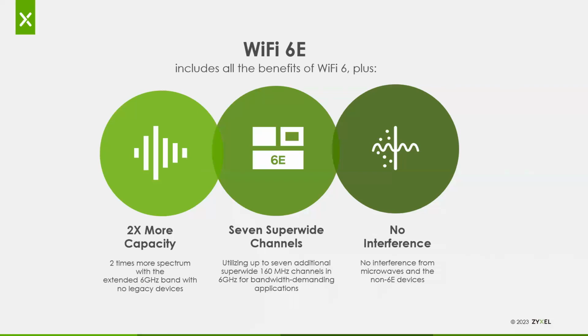But that does lead us to one key thing when it comes to Wi-Fi 6E and 6 gigahertz usage: essentially at this point, 6 gigahertz can only be used indoors. There is a new technology that is going to be part of being able to use 6 gigahertz outdoors. It requires you use a third-party service to be able to geolocate where you are, what channels you are currently using, and what channels other people, legacy users, may be using. So it can basically have you switch channels if a legacy user comes into the space that you're at, or to prevent you from using a channel that's currently being used by a nearby legacy user.